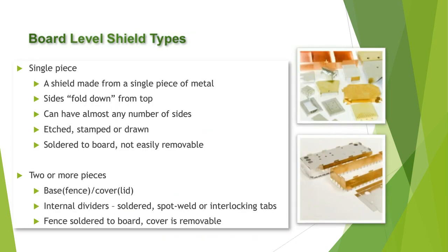So what are the next steps? You've already decided what frequencies and what materials you're going to use. Another decision you'll have to make is, are you going to have to get underneath the shield at any point? Or is it the type of application where you'll be able to place the shield and just leave it? A single-piece shield has a number of advantages. Well, I guess mostly one major advantage, which is cost. It certainly costs less than buying multiple pieces. But there is some ease and simplicity of construction as well.